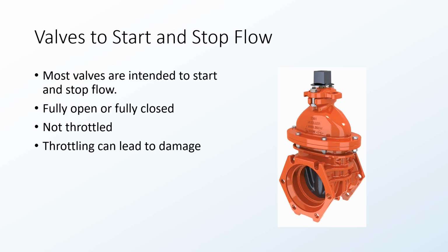Initially, when you're starting and stopping flow, you want to do those things slowly to prevent water hammer. If you allow too much water to flow initially, or if you shut flow off too quickly, you can create water hammer, which could damage your system in some fashion.